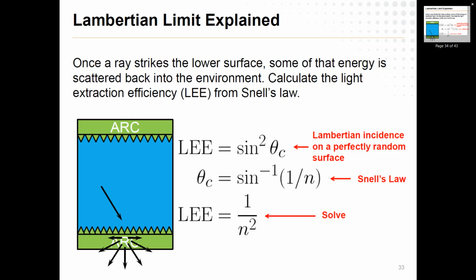So imagine if I have a very, very thick dielectric with a high index of refraction, very, very little energy will fall out here and the rest will reflect up. But if the index of refraction is very, very low, it's kind of like an impedance matching, and I lose a lot of energy here. So thankfully, silicon has a pretty high index of refraction. 3.5 is relatively large, and you get roughly this 1/n squared factor for my light extraction efficiency here.